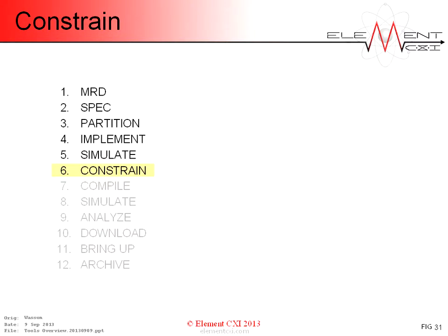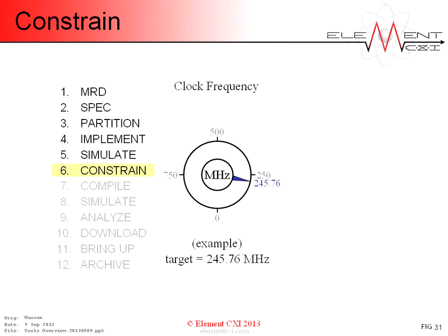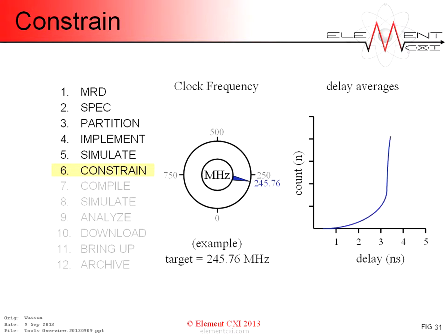One vulnerability to such simplicity is the tendency to over-constrain the target frequency. For example, given a target frequency of 245.76 MHz, the standard FPGA route result has a net delay distribution curve. Some fast, some slow, most in between, but all hopefully under the prescribed 4.069 nanosecond max. Designers inclined to gain margin by cranking up the clock constraint to something like 300 MHz will find that while most nets might meet the new 3 1/3 nanosecond constraint, a few nets will fail the real 4.069 max requirement.